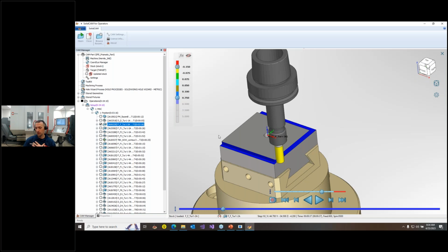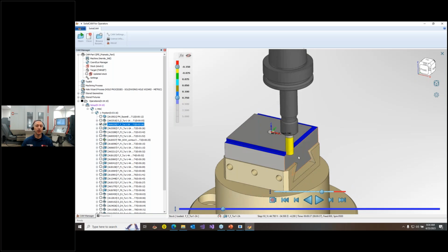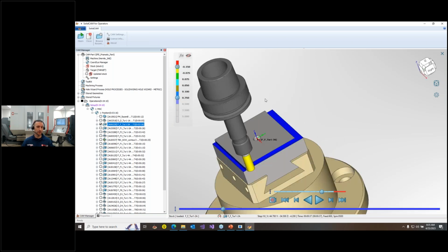So as an operator, you have to decide, was that okay for me? Am I okay with it wasting a little bit of time air cutting? And if not, then you go back to CAM programming and say, hey, listen, I tried to make a modification here. I tried to add an extra pass, but now it's air cutting on the right-hand side. Could you optimize the program, which would be something like: do one pass along the back wall, one pass along the front wall, then come in and add that, then keep the pass that we have that cuts one pass around the entire thing.